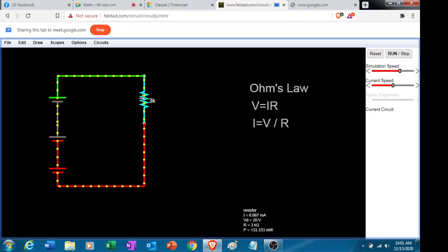Can you see it, guys? You can try to zoom. So what's the value? 20. Very good, 20 volts. So if the batteries are in series, you're actually adding up their voltages. This one has 10 volts, these two have 5 volts each. So 10 volts plus 5 volts plus 5 volts, that's a total of 20 volts.